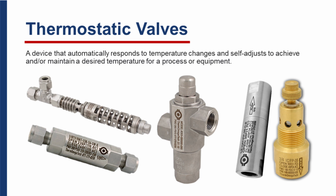On the right-hand side, you'll see two other two-way inline valves that are used on the other end of the temperature spectrum for freeze protection. When the temperature drops to around 35 F or so, the valve will open up and allow warmer, fresh supply water to come in, and it would close back off at 40 degrees, and it would modulate back and forth between 35 and 40 degrees.